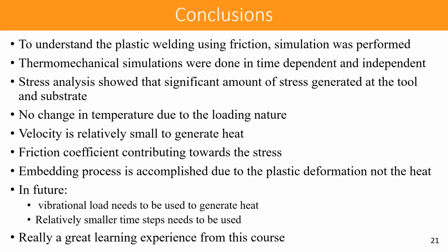This sort of information we can certainly gather in the future. And then we have to use a relatively smaller time step to assign the vibrational load, and this is a really important thing about transient analysis: setting up the right time steps to determine the effect of the time dependency of the entire simulation.